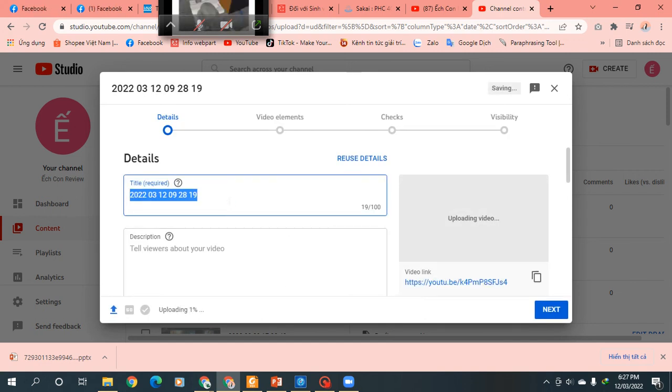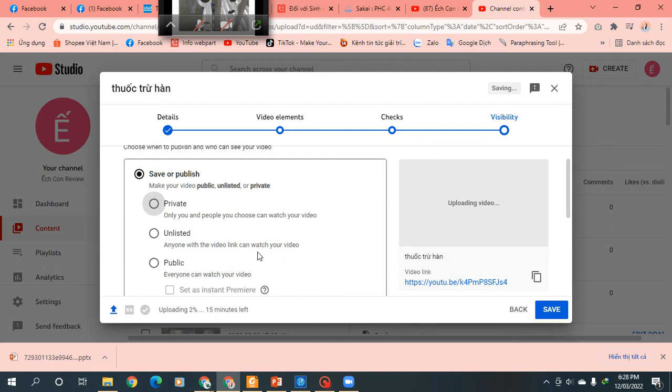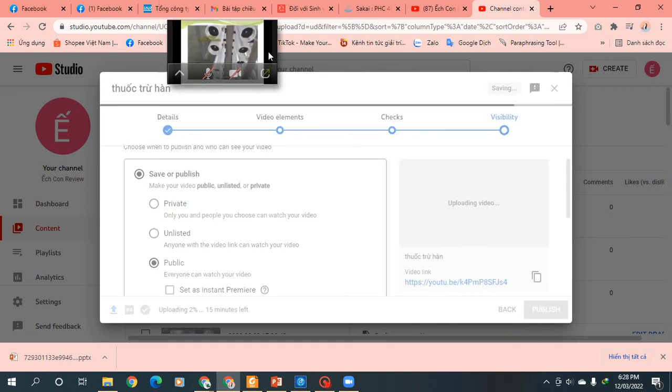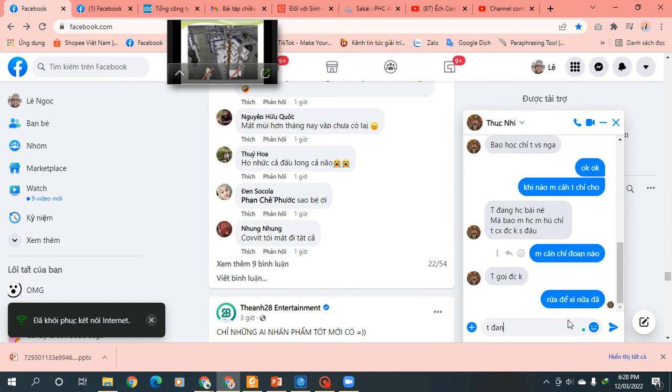As with the first stage pressure vessels, there are 2 exiting flow paths from each second stage pressure vessel. The flow path which exits the side of each second stage pressure vessel is part of the second stage concentrate outlet flow. This flow path consists of the concentrated reject water from the first stage of the RO, which was further concentrated in the second stage of the RO. Second stage concentrate flow is the final reject flow of the RO system when it is in operation.